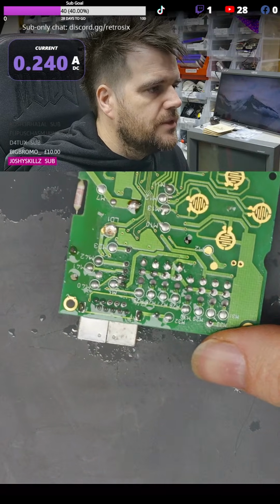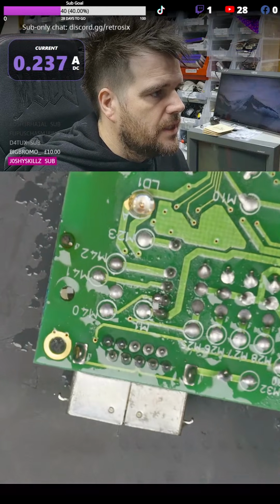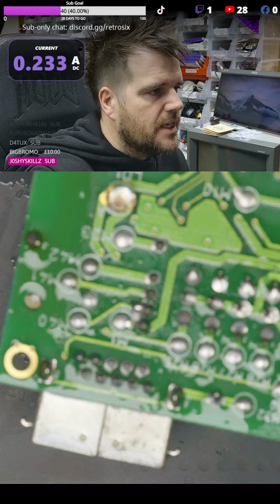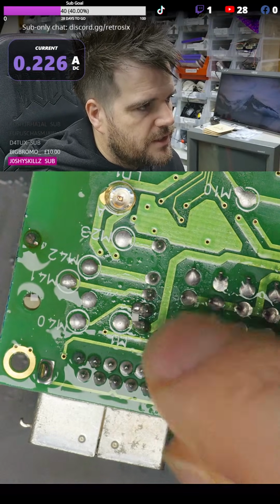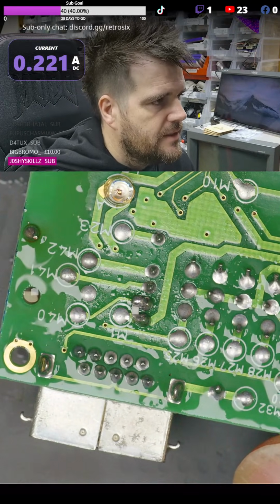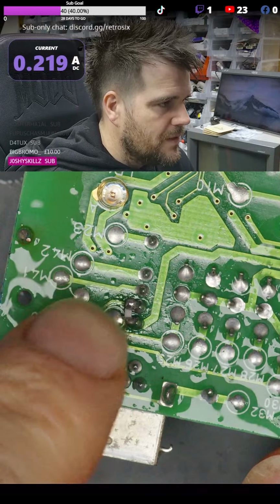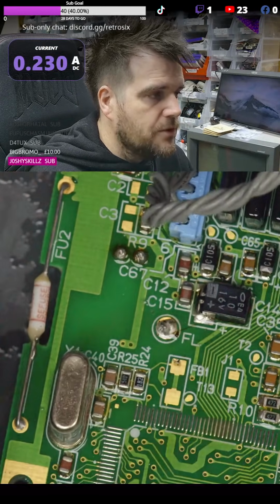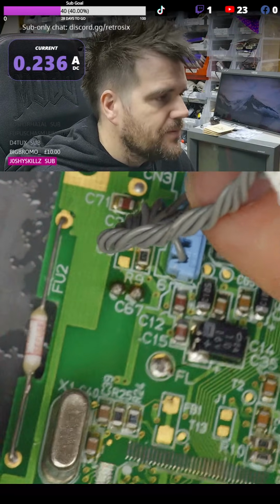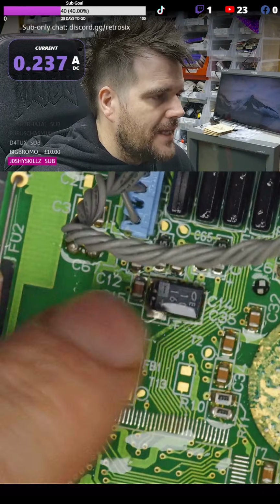So the short I've done is a fairly simple short here, and this could happen to you by mistake or for real. All I've done is put a literal 95 ohm resistor over the power pins here. This could have flown off for you, but what this is simulating is a capacitor actually slowly dying. It would simulate very similar behavior, and that's what we're trying to detect.